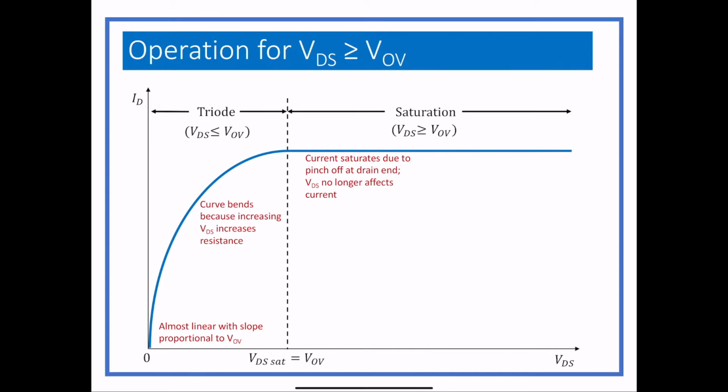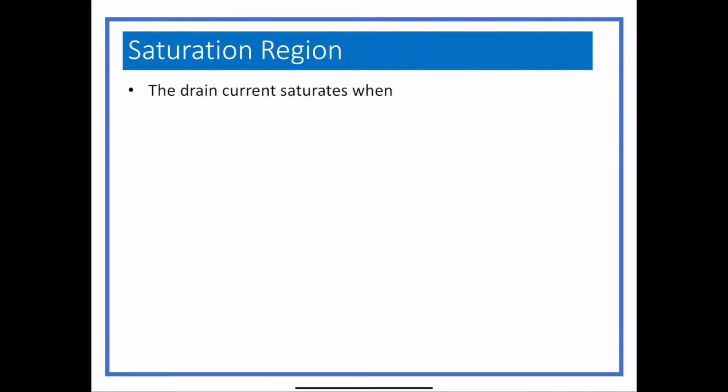You operate way above or way below. So the drain current saturates when VDS equals the overdrive voltage, which technically, yes, for that sign I should have had plus, greater than, and less than, and no equal, but whatever, I don't care. You shouldn't either.